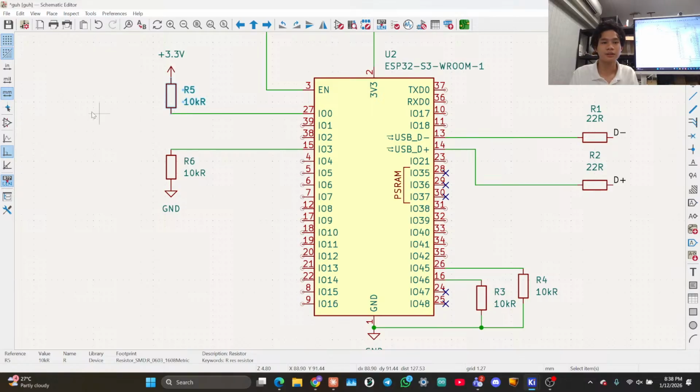If they aren't in a known position, they will go haywire and the application won't work reliably. So you want to ensure there are reliable inputs on those pins when it starts up, and later, because it's a pull-up resistor, you can just use it as a normal GPIO, albeit with slightly different properties. For that pin IO0, the boot pin, you do not want to leave it floating, which is not connected.